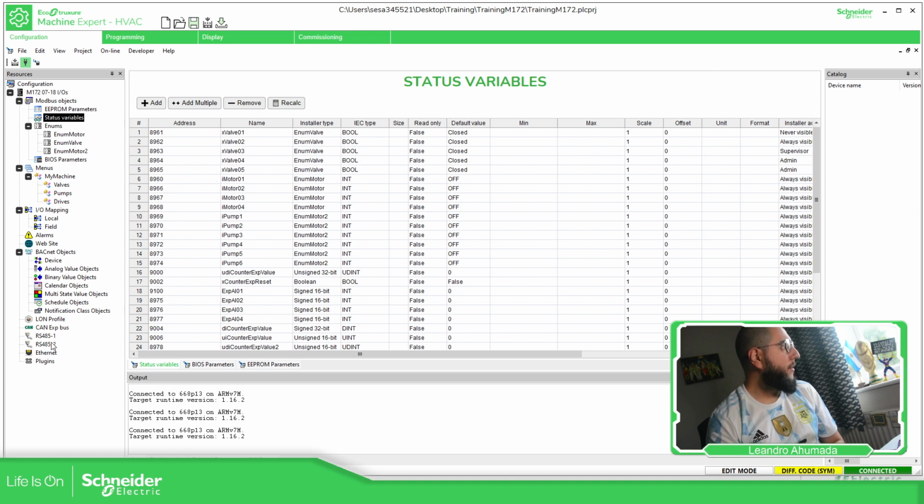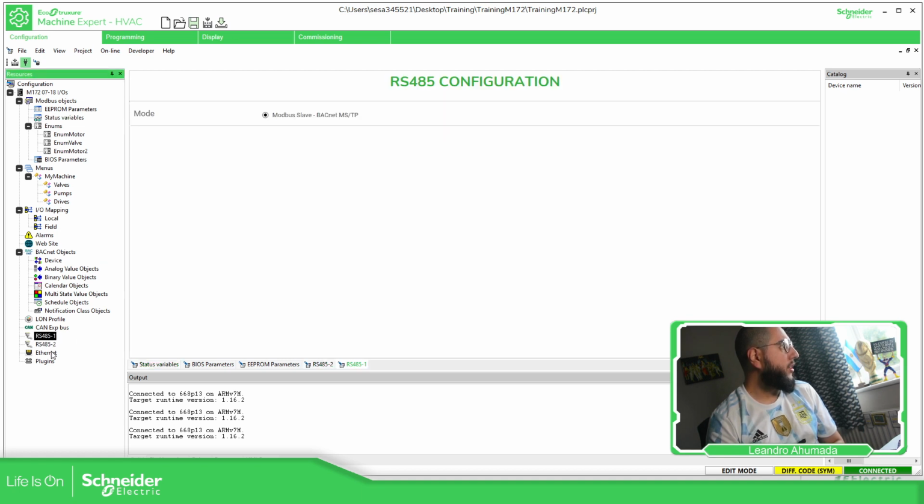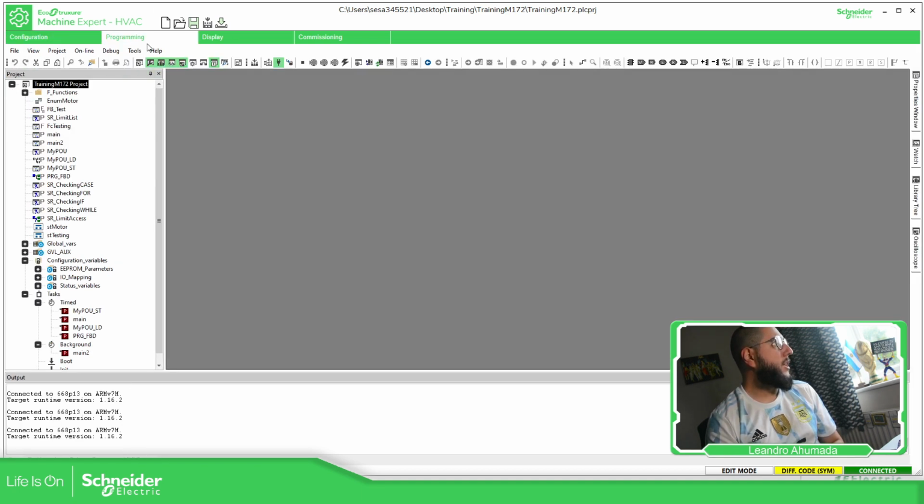In case you have different communication settings, it will generate the file, for example the connect.par, which is the one that has those configurations for the device. So if something doesn't make sense when you only download the code, then probably a Download All is going to be the best.